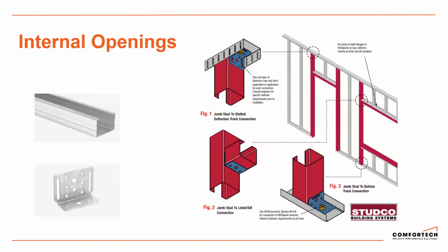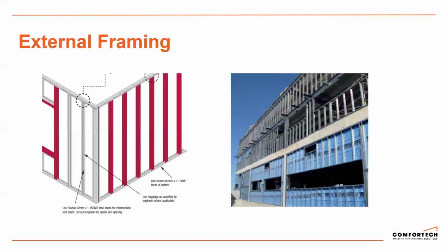There are proprietary heavy gauge brackets and fixings, brilliant for around doorways and around openings for windows because they've got that structural strength. So a really good way to stiffen up a wall is to use this heavy-duty stud. That same framing can be used for external non-load bearing partitions. So this is in between your portal frames.